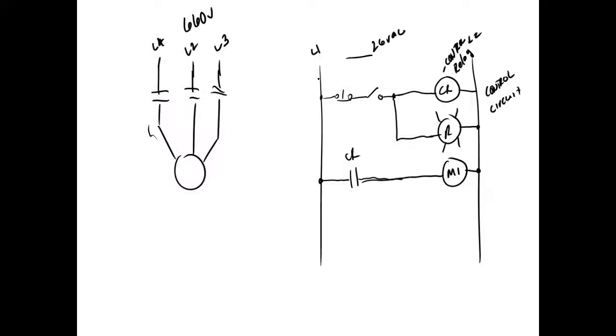So normally in controls, in true prints, they don't usually call that L1 and L2. I think in US Steel prints, they call it PL1 and PL2 to let you know that that is not the L1, L2 and L3 three-phase. Well, this over here would be my power circuit, and this might be controlled by M1.